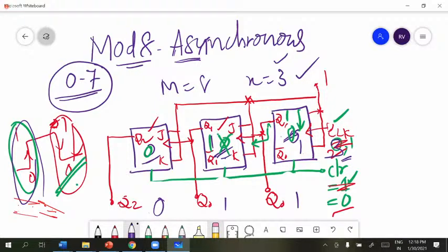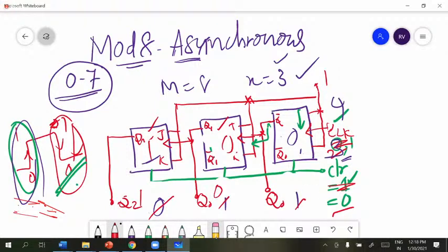When the fourth clock pulse is there, this 1 will become 0. Always the first flip-flop output toggles, as I said. As 1 becomes 0, because of that negative change, this also toggles. So this 1 will become 0. And that 1 becoming 0 is a negative change. That is applied to the third, so that flip-flop output toggles. Okay. So you can see this as 1 here. So this entire thing appears as 100.